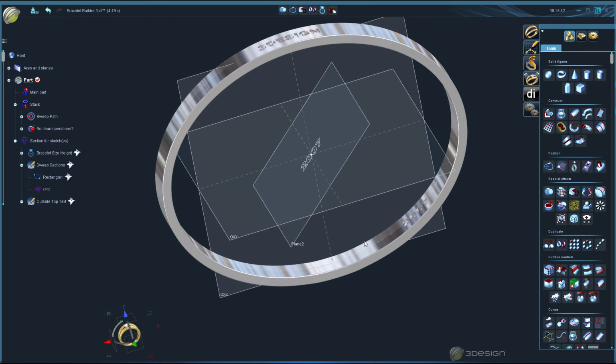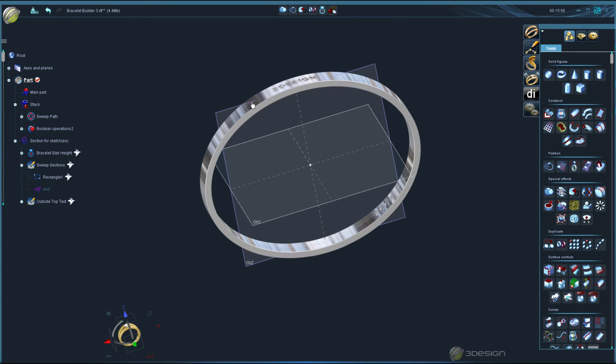So just setting up some different examples for you. Now you can do the same thing if you want to put more cutouts on the corners on the outside or more on the inside. Set up as many planes as you need for your builder so it does what you want it to do. I'm going to hide my sketches again. And now we'll do some testing to make sure our parametrics are working, our history is all built correctly.